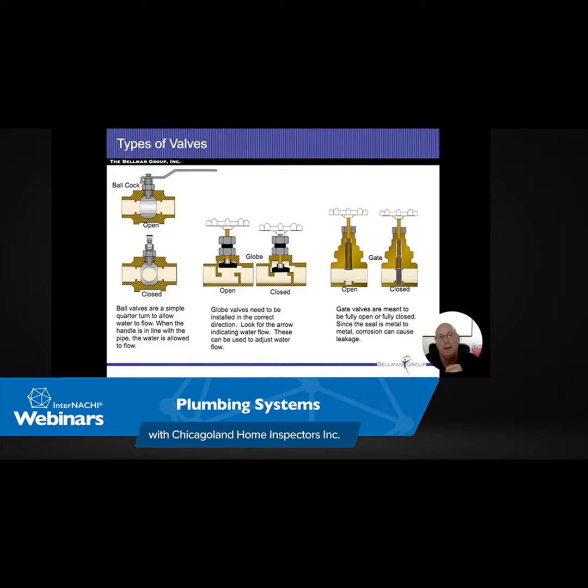But now if the water is going the other direction, and I keep forgetting that I'm reversed on the camera. So the water is going the other direction. If that valve isn't open all the way, then that water is going to keep hitting that valve, and we're going to end up getting water hammers. And again, it's going to sound like machine gun fire. You're just going to hear boom, boom, boom, boom. That's the valve just constantly opening and closing as the water pressure keeps changing and going back and forth. So if it's in the wrong way, you've got to get that thing all the way open.